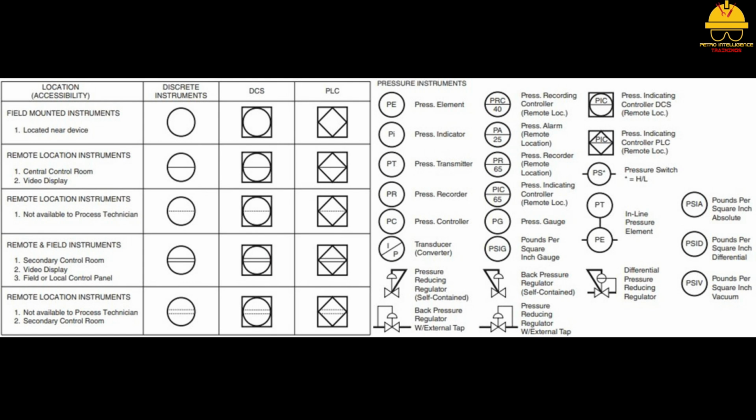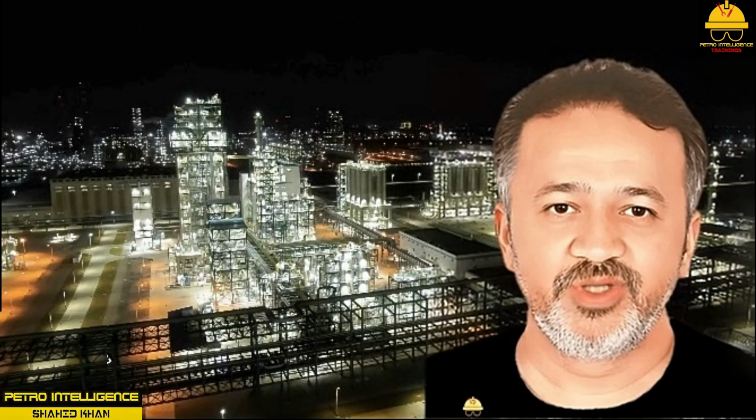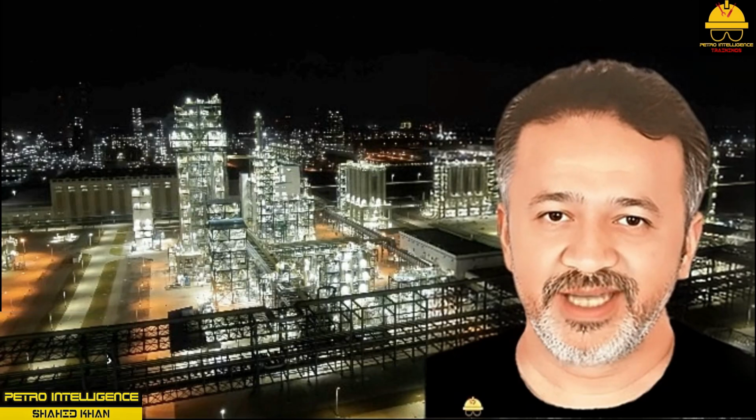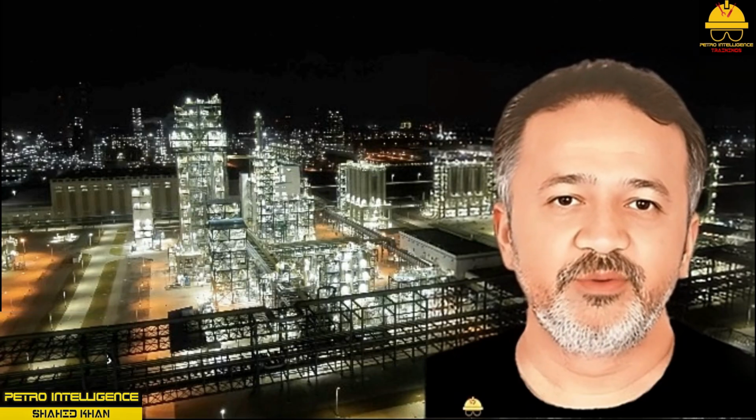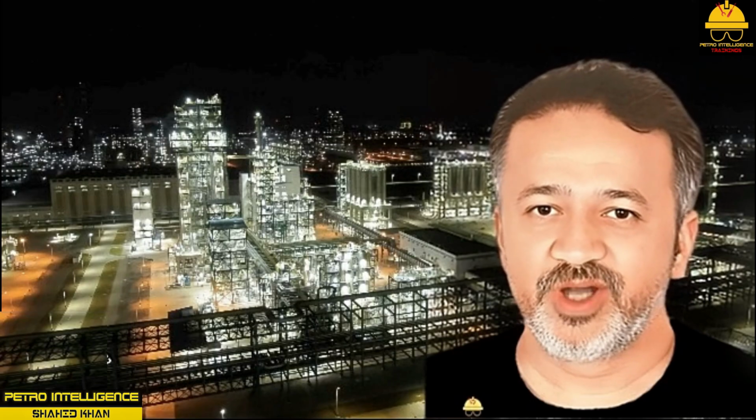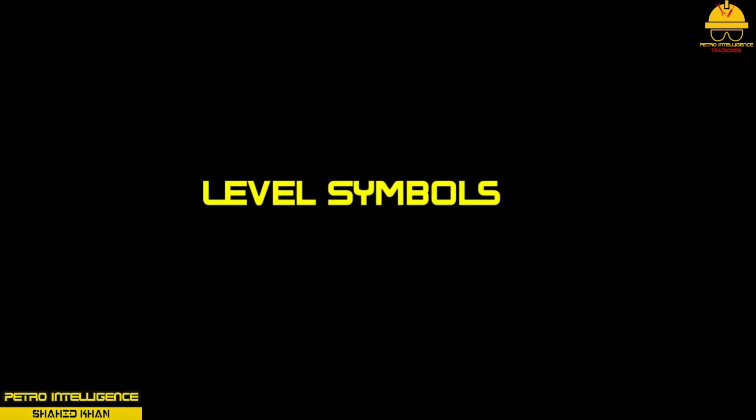Pressure is typically controlled with a pressure control loop, PIC. In this system, each of the 5 elements of the control loop will be pressure-related and labeled appropriately. It is also possible to have other pressure symbols like pressure recorders, PR, high-pressure alarms, HPA, and low-pressure alarms, LPA.